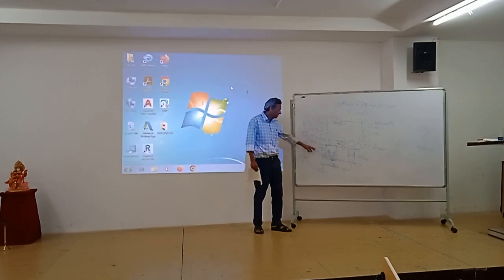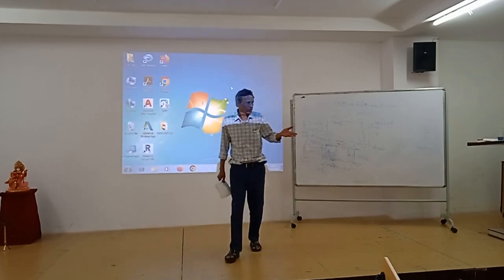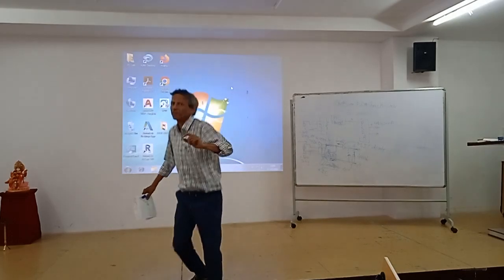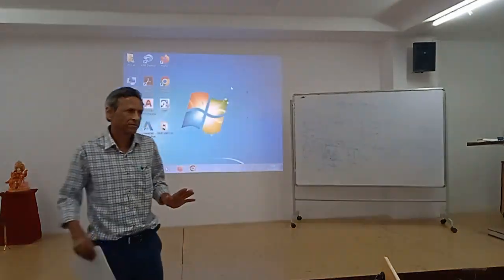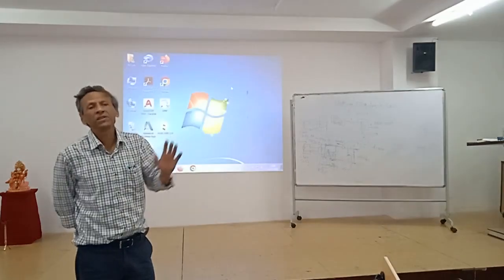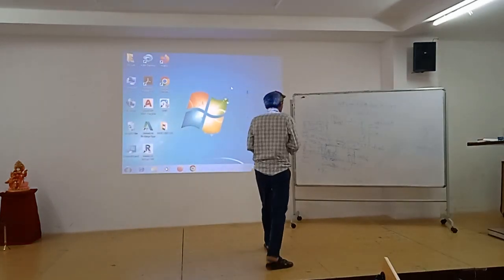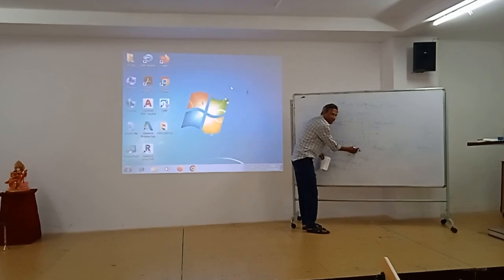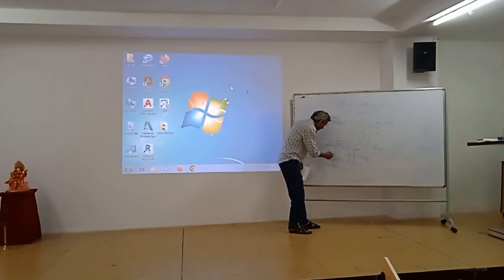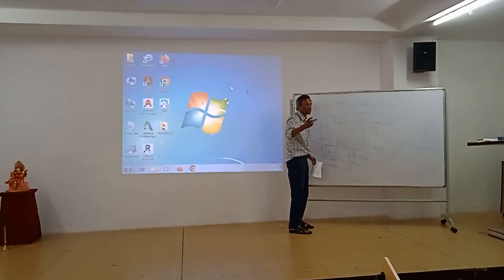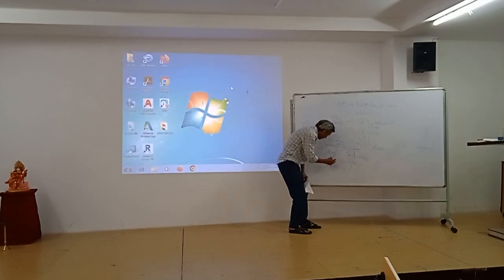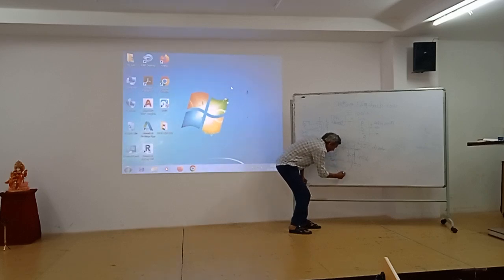What is the disadvantage? Extra loss, and switching harmonics will be there. That's why, see, that's what he was referring to. Even if I am handling 10 kilowatt of power, what is the PWM switching frequency? Because now my ripple will be at the switching frequency. Suppose for silicon IGBT I am taking 15 kilohertz. This is good enough.